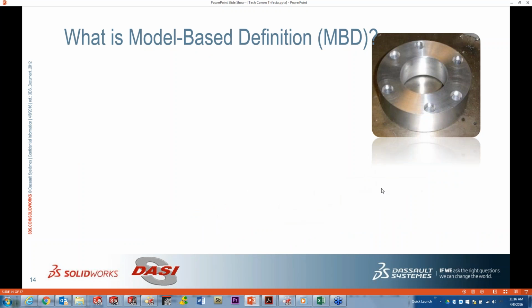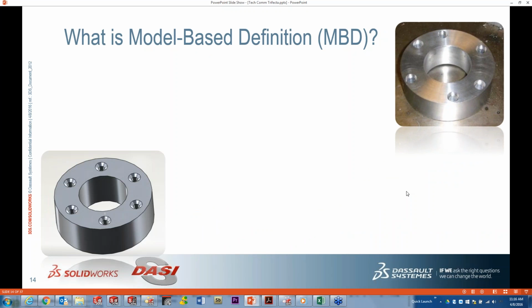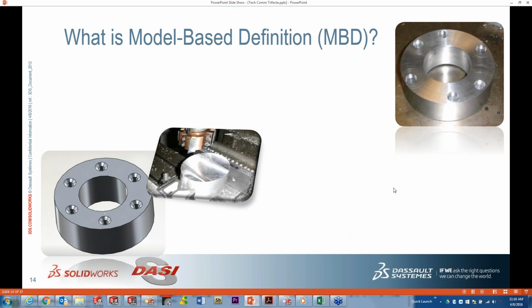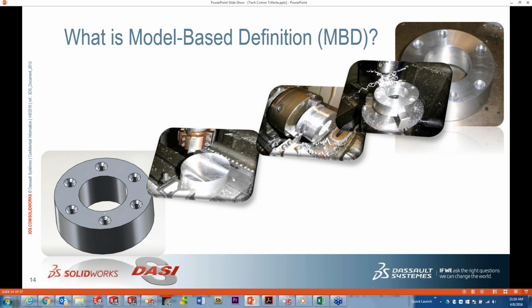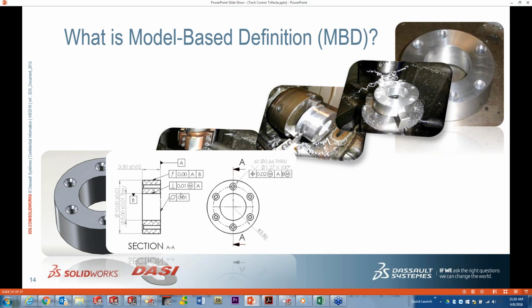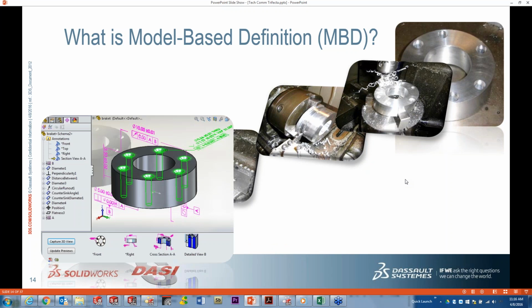We take this part that we're intending to manufacture and we create it in 3D CAD. Now in 3D, that file is then taken from a billet of aluminum, we machine it in 3D, and we end up with a 3D part. But all along, we've always been using these existing methodologies, taking a 3D file and flattening it out into this 2D communication tool. We've been doing that for years. Well, why not just take your 3D file and also annotate it in a 3D way. The way that's more universal, it's more visually appealing, and we're not having to duplicate efforts by making a 2D drawing from something that's 3D so that we can convey how to build it back in 3D.